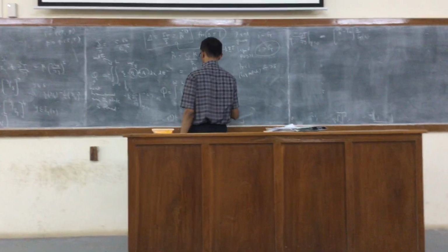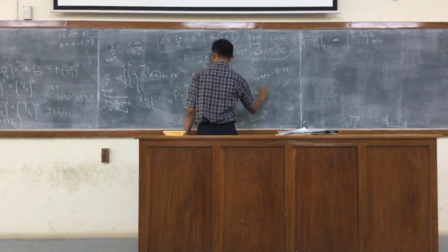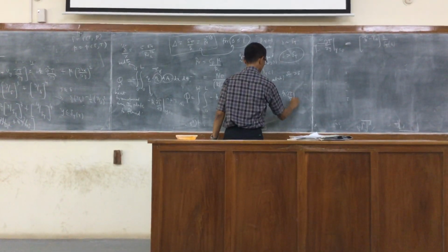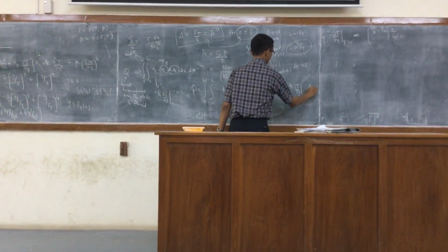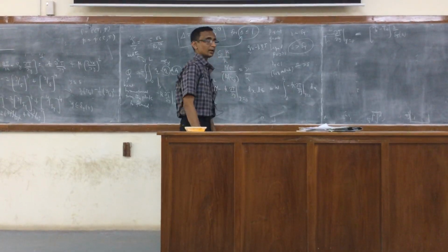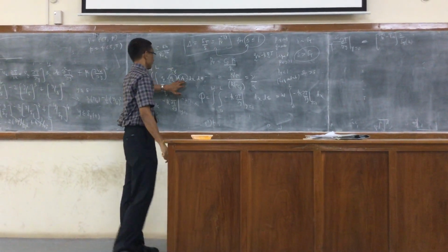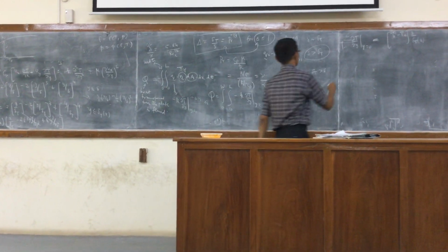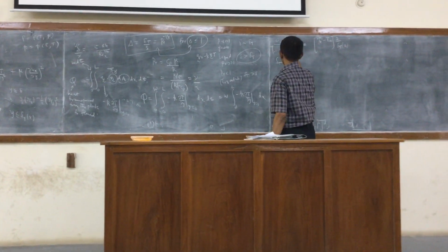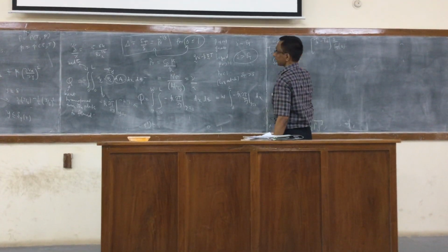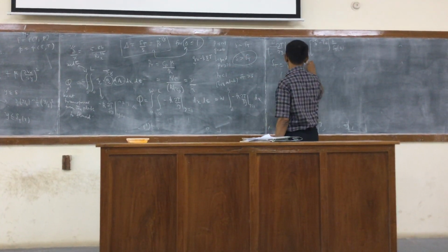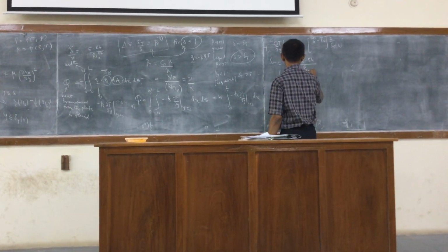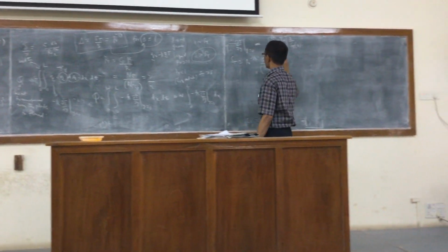So I can now write this as simply w times the integral 0 to L dx. So that is where the dependence on x comes. So I have to simply rely on this. So delta T I will take to be Prandtl number to the minus 1 over 3 times delta, which is 5.84 x by Re_x to the half.